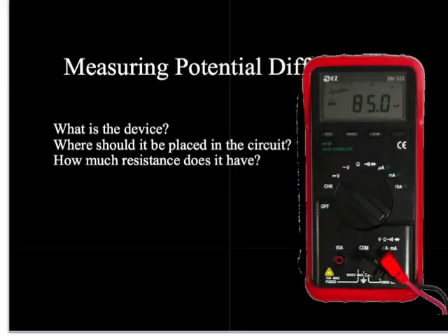How do we measure potential difference? Well, this device, remember, is a multimeter, but when you use this setting, okay, it is a voltmeter. And remember, there's actually 2 voltmeter settings here. There's DC and AC. So you hardly ever use the AC. Okay, this one, actually, if you notice there, it actually says millivolts. So you've actually got to be aware of what is on the screen when you're measuring the voltage.